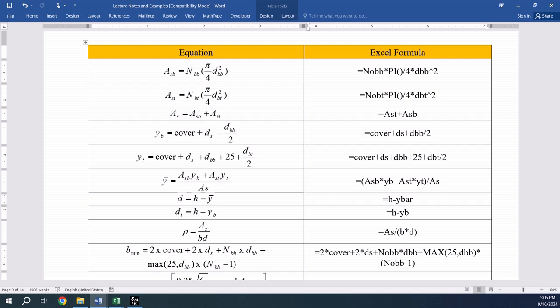This is a very important step because we are condensing our structural engineering knowledge and pouring the results into cells that will perform all of the required calculations. Not just that, but these cells in the Excel template will then determine whether the section is adequate or not. If adequate, the Excel template will present the flexural design strength of the section, and if not, the Excel template will indicate that the section is inadequate and the design strength will not be provided.